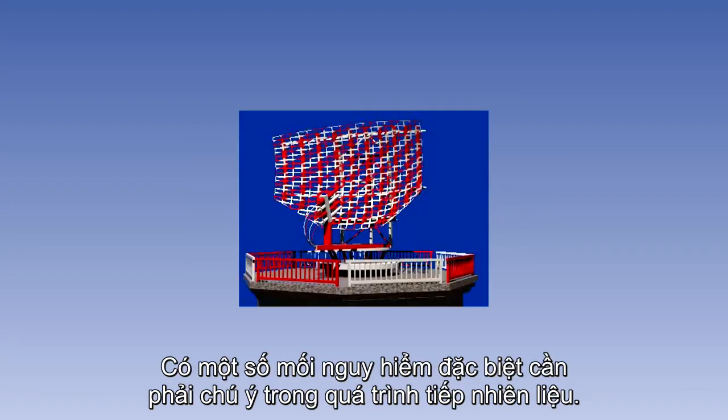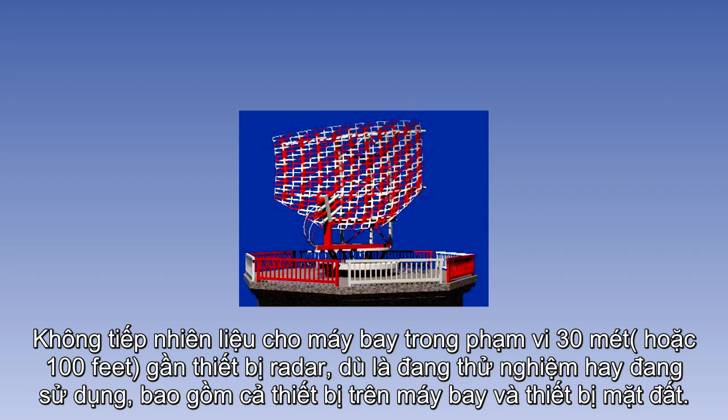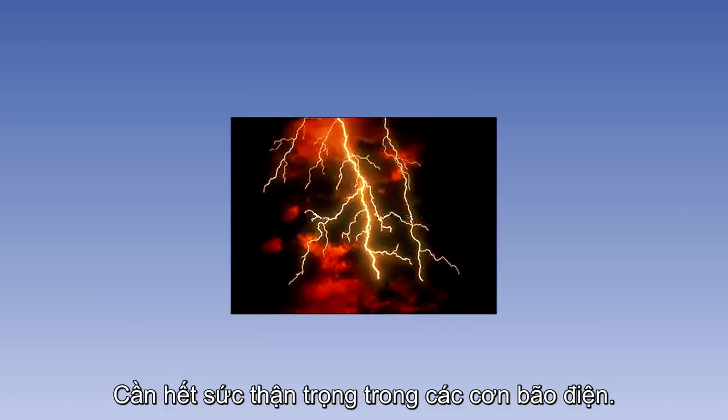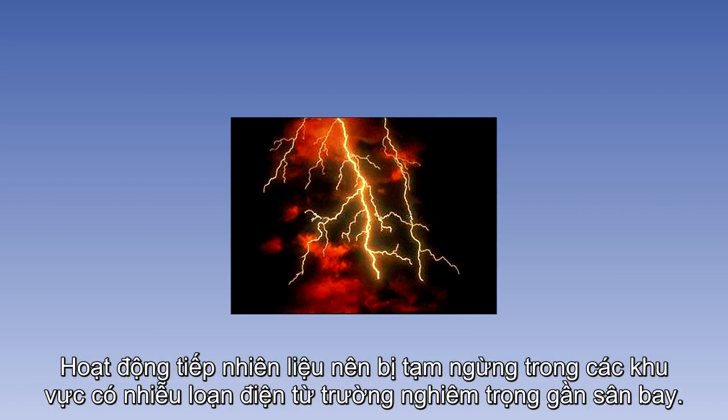There are a number of special hazards that need to be looked out for during refueling operations. Aircraft should not be refueled within 30 meters or 100 feet of radar equipment, either under test or in use, in either aircraft or ground installations. If the landing gear is overheated, the aerodrome fire service should be called and no refueling should be carried out until the heat has dissipated. Extreme caution should be exercised during electrical storms. Fueling operations should be suspended during severe electrical disturbances in the vicinity of the airfield.